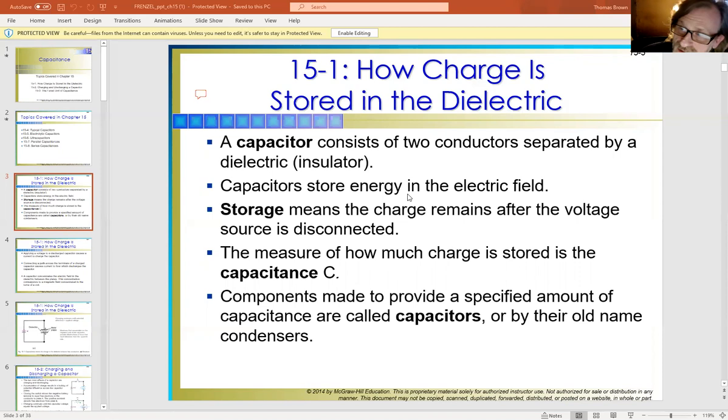You can exceed the charge if you have a voltage applied across a capacitor that's more than what it can handle. In some cases, they will explode. Some cases, they just burn up and make a lot of smoke and smell extremely bad. But yeah, if you do exceed the voltage rating on these things, they will degrade. The dielectric breaks down, and then it's anybody's game.